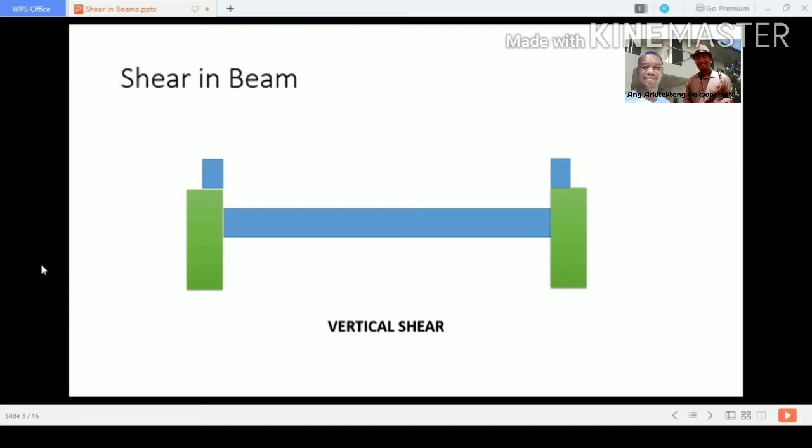So vertical shear force is usually represented by the capital letter V. In computing its values in the examples and problems, consider the forces to the left of the section, but keep in mind that the same resulting force magnitude will be obtained with the forces on the right.